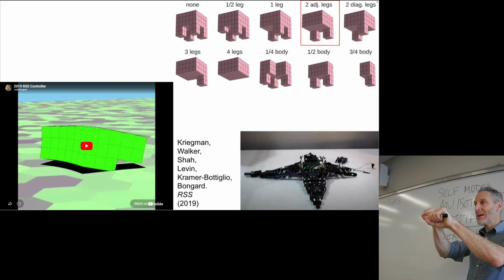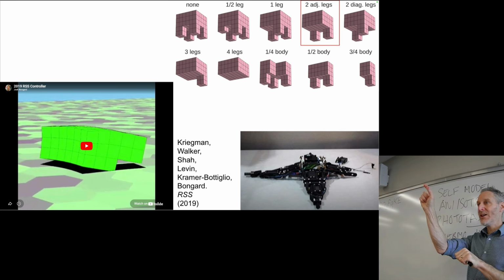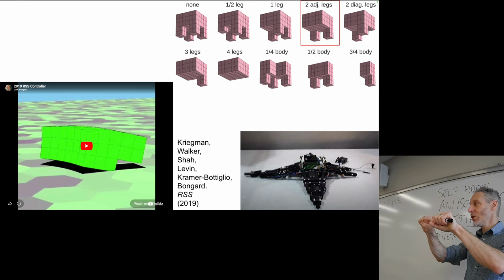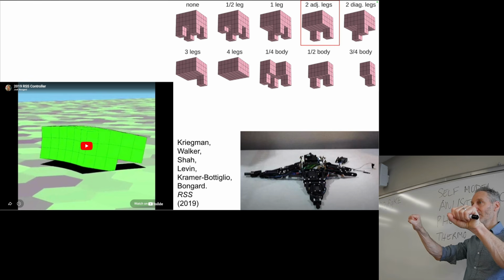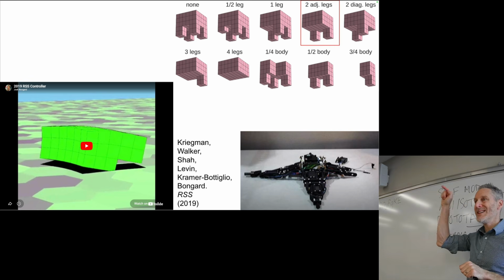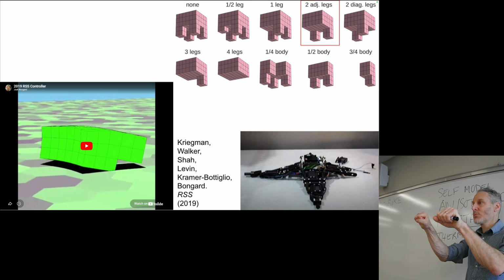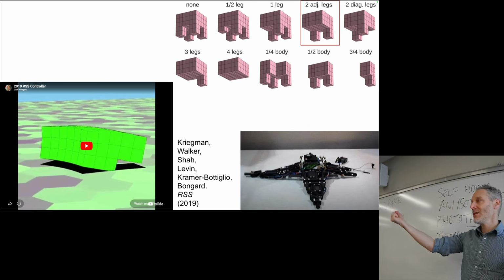We talked about chopping that beam in half and assuming there's a spring connecting those 2 beams together. A positive value at the motor neuron says, extend the resting length of the spring. Make the spring want to be longer, which results in the beam elongating. If the value in the motor neuron is negative, that negative value is saying contract or reduce the resting length of that spring. That spring will now try and shorten, and it will pull the 2 ends of the beams together.